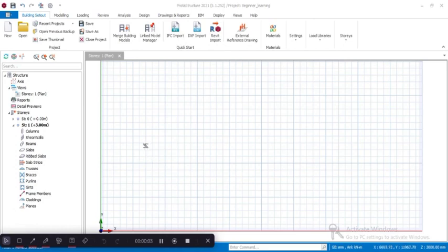Please select the unit of the Excel file you load. Just a continuation of the explanation: story information, and select the story on which the model is to be generated. That's important because if you click on another story, if you want to use the DXF you imported on story 1 and you're on story 2, it will appear on story 2 and it will be a different thing on story 1. So it has to be on the story where you want to import those. You have to specify where you want to import the structural members and other things. So you can go through that.